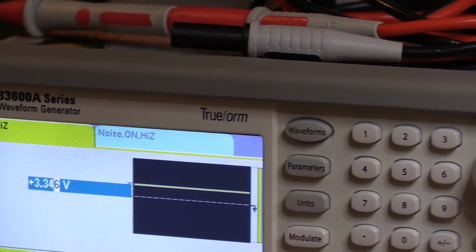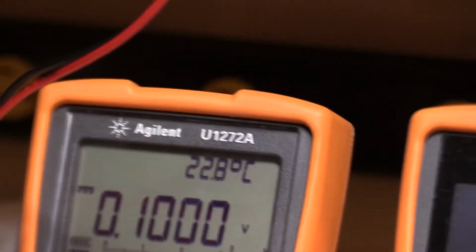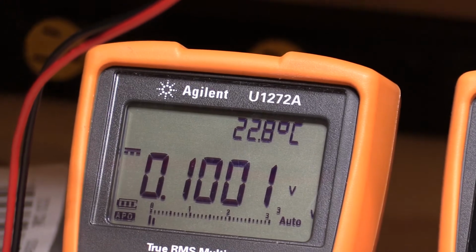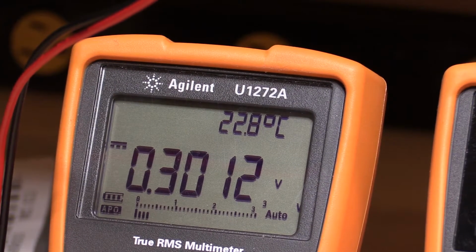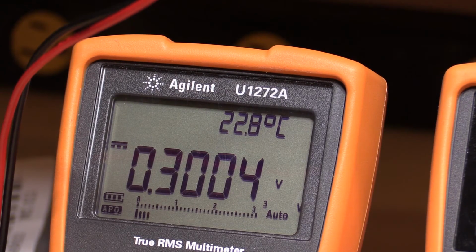And if I now increase this so that we get 3 amps on the meter, get the right meter, there we go. So we have the high end of our DC. So we're just doing this with a DC voltage on the gate of the MOSFET right now so that we can just find out where our limits lie. So that's pretty much close enough right there. So that's 3.884 volts on for the high side.